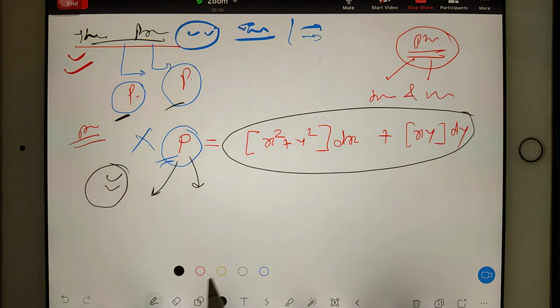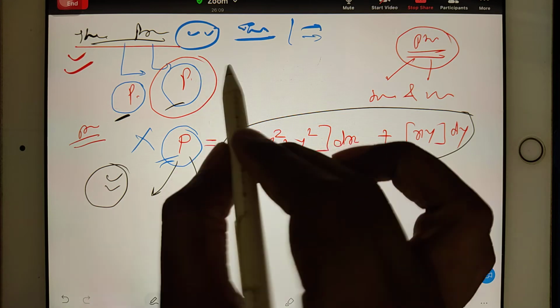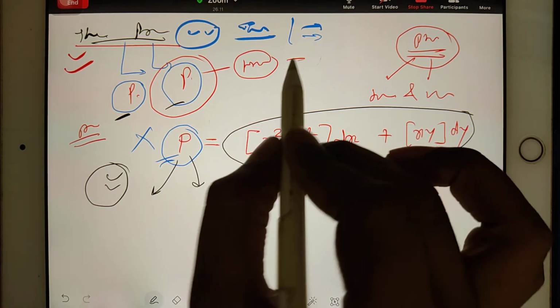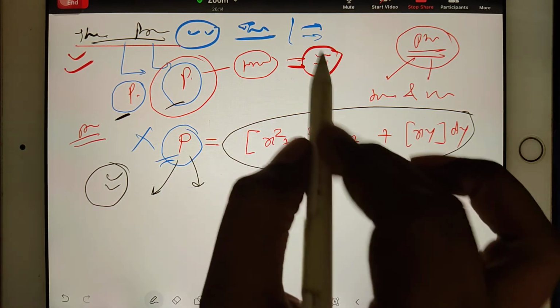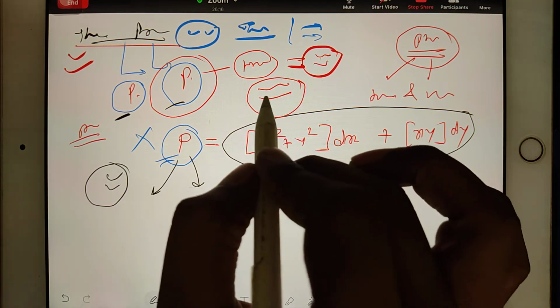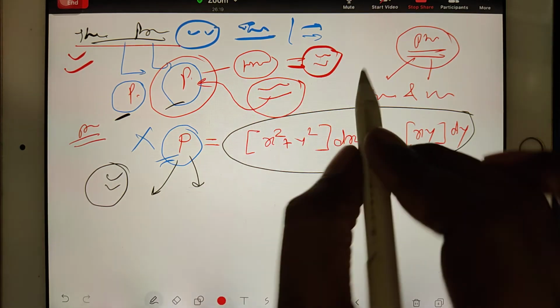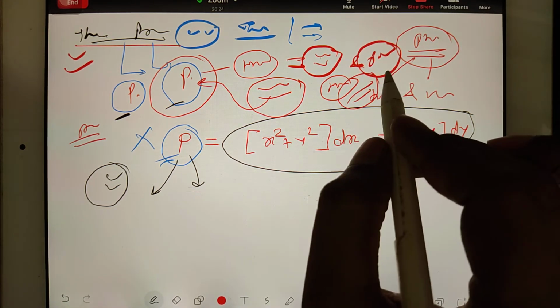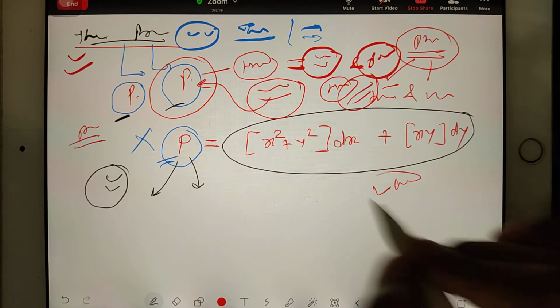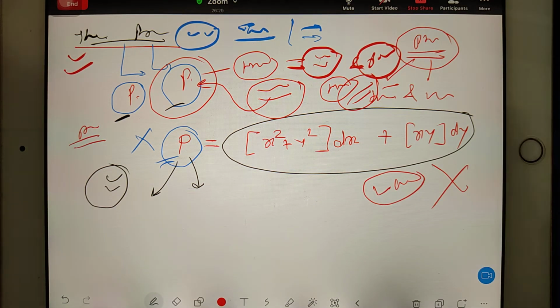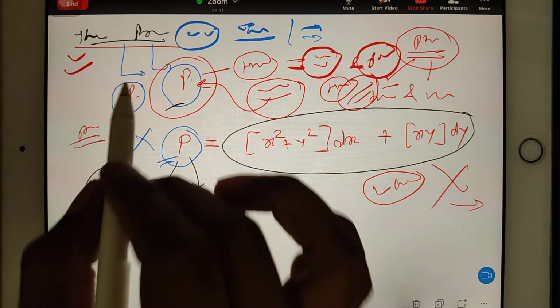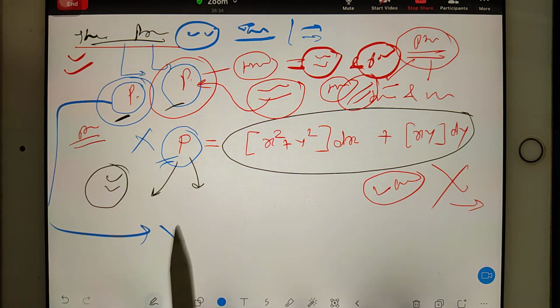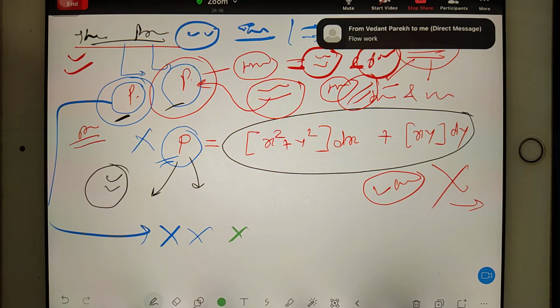Directly, what is a path function? Whatever properties you can't store, whatever properties you can sense only at the boundary of the system, those properties we call path functions. The best examples of path function are heat transfer and work transfer. Very soon in the upcoming part of the lecture I will explain. There is one special work that is not an example of path function; I will explain in the upcoming lectures. Now see, a point function is very clear. It does not depend on the path.